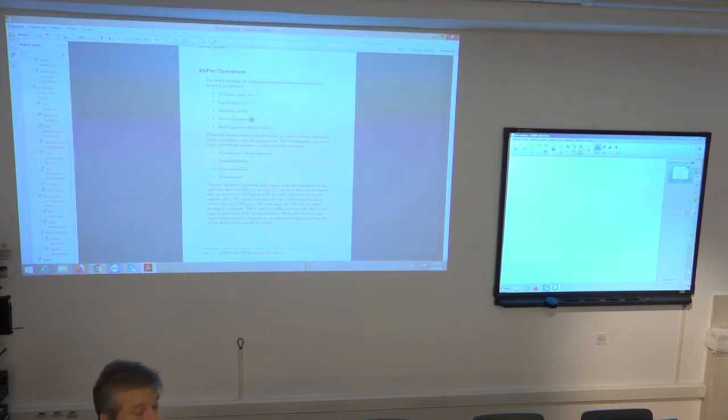And after this instruction, this value is written to this SE register and used as a control value to shift the input value, either left or right, sorry, only left, because normalization is only left shift. And it performs left shift, arithmetic left shift.